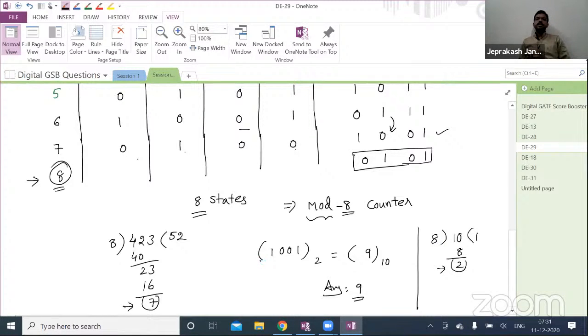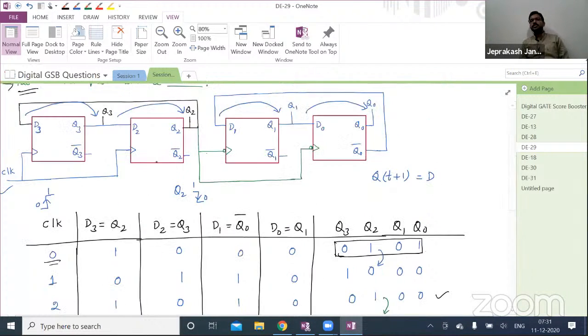Okay, so this is the conventional approach to attempt any question related to sequential circuits. Whatever flip-flops they have given, regarding those flip-flops you have to determine the inputs here, and for each flip-flop write the outputs here. Before applying the clock pulse, whatever the state is, you have to consider. With respect to that state, you can determine the inputs before applying the next clock pulse. When you apply the next clock pulse, positive edge or negative edge, before that particular edge, what are the inputs you're having? Based on that, your output will be affected.